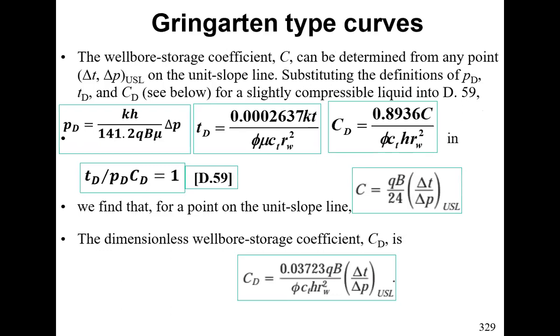So the wellbore storage coefficient C can be determined from any point on the unit slope line, with subscript USL denoting unit slope.